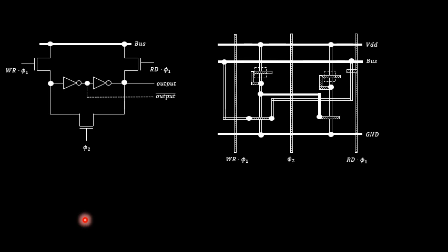Also, we discussed the concept of the three transistor type of dynamic memory cell, and how to design them by making use of NMOS logic or CMOS logic depending upon the application. In all those concepts, we have studied that the data stored in the form of charge in the capacitor will be retained as it is unless there is a lapse of 1 millisecond of time duration.